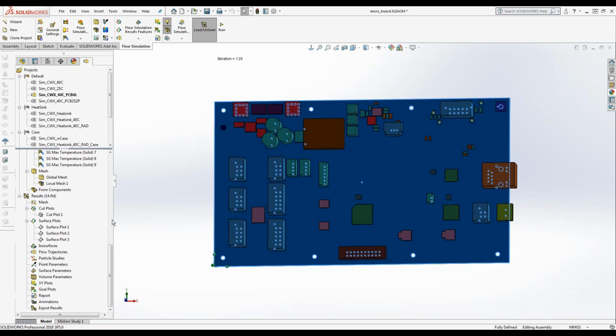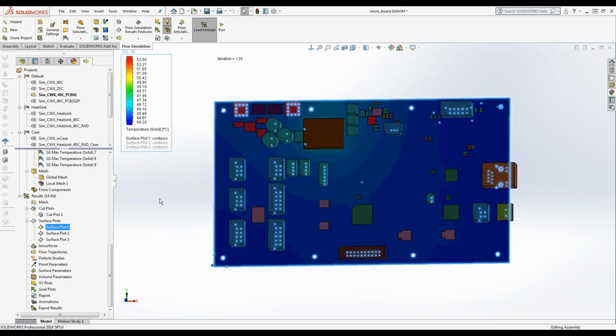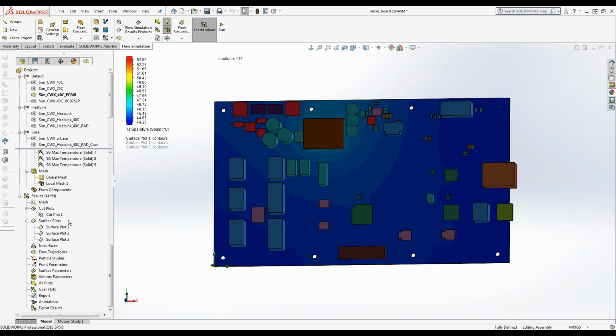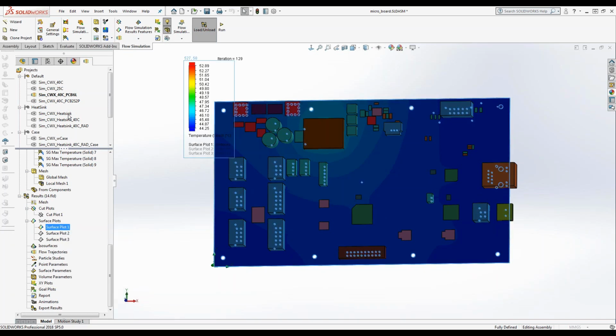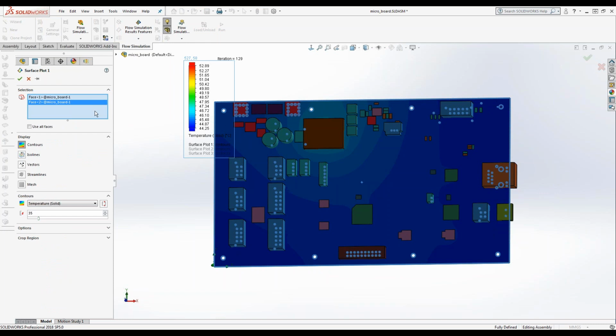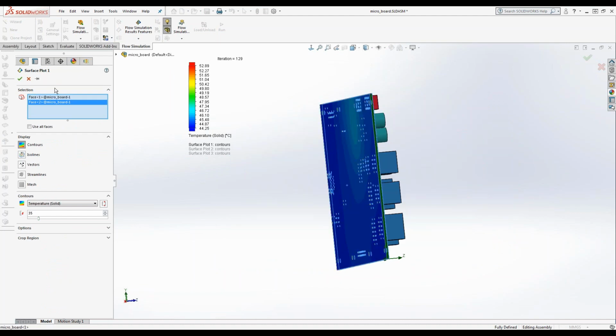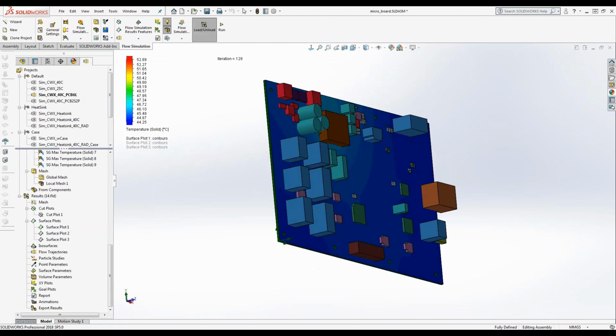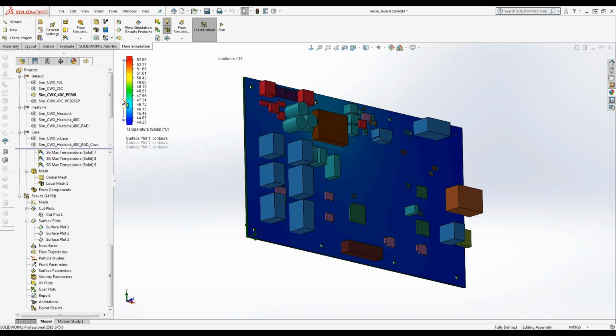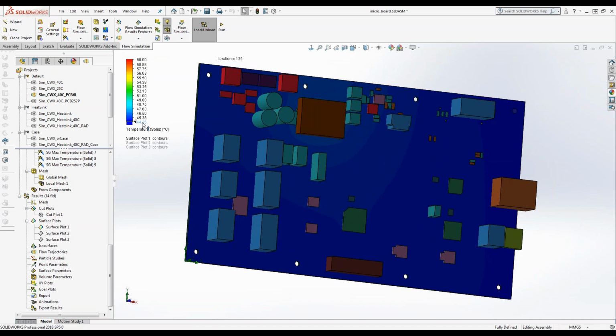The surface plot, so here what I'm doing is I'm looking at, for example, what are my solid temperatures? I've gone in and I've selected in this tool here, I've actually told it, I want to know what is the temperature of this and this, for example. So I put my faces in, I set it up for please display temperature. I want about 35 gradations in my scale, and I can always, of course, change that kind of stuff. I can make things coarse or fine. I can change limits. So this tool allows lots of variability. I can move colors around.